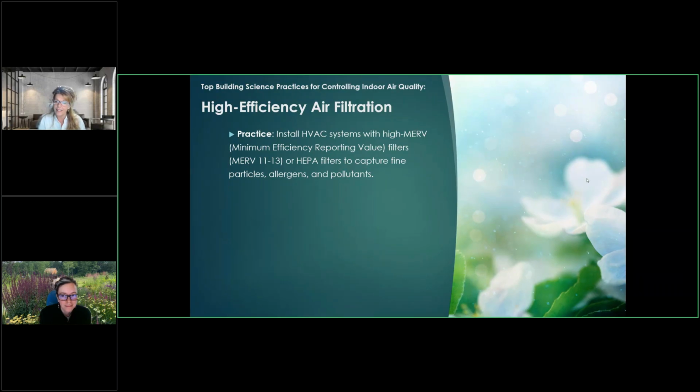But the reality is if you do this during the humid seasons, you are actually going to be making your homes more humid because running that fan is going to be evaporating the water off the coils on your AC system back into the living area, the living space. So you've got to be careful with the strategy on using these.